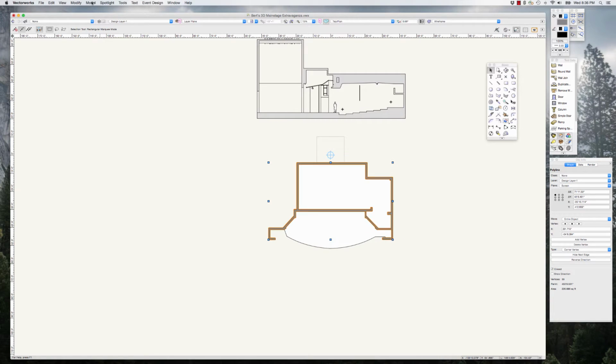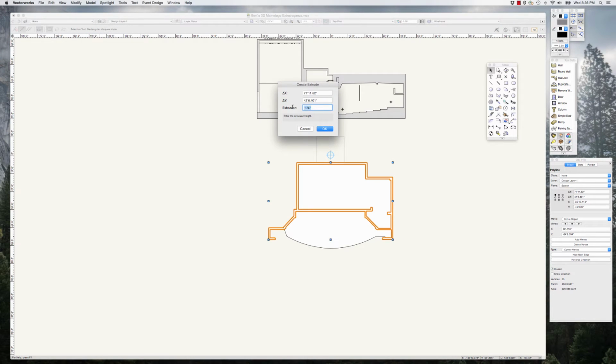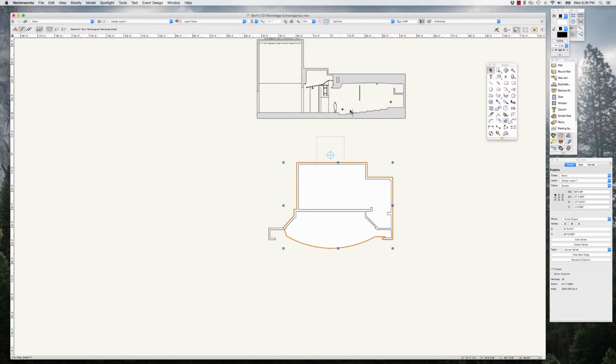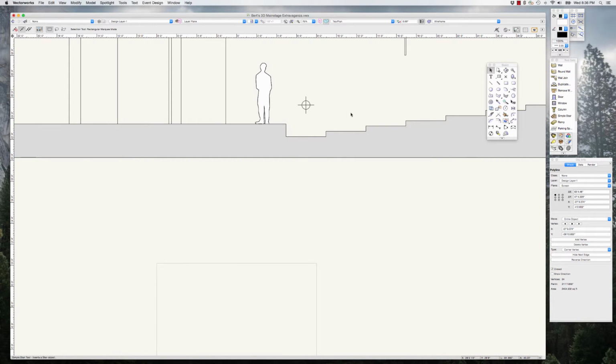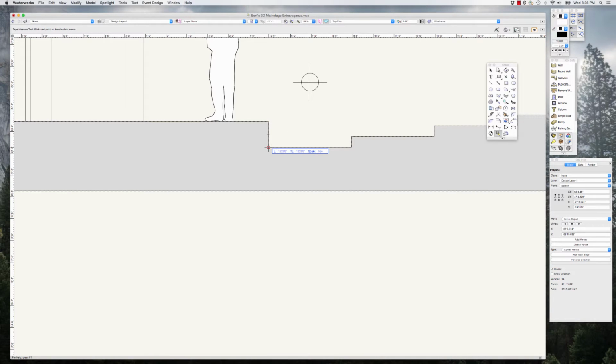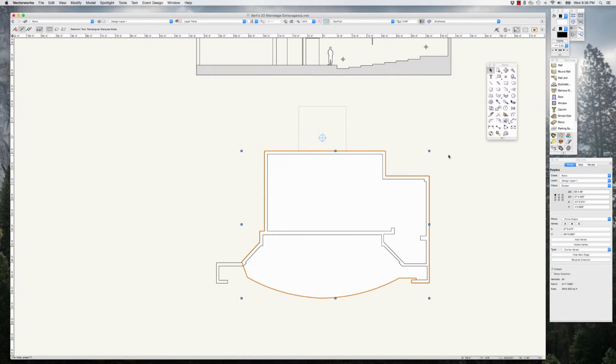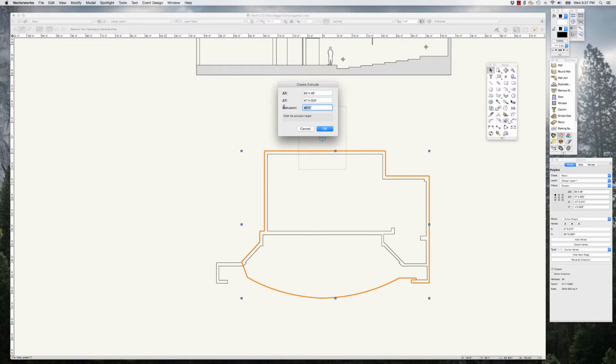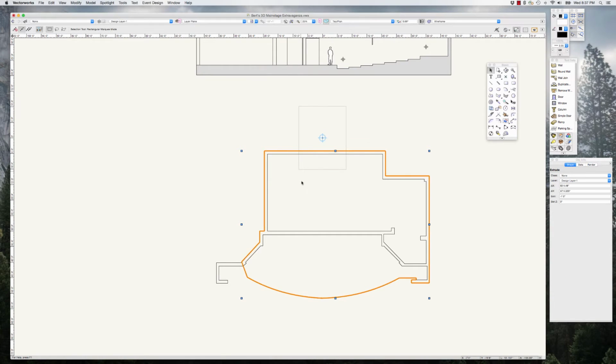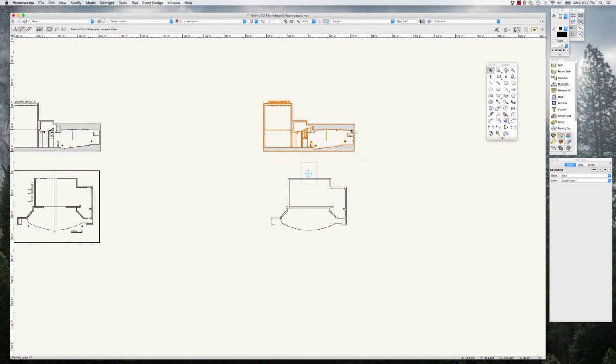So we're going to extrude this 40 feet. Model, extrude, 40 feet. Okay. And then we're going to extrude the floor down, and we're going to go down this distance, which I think is 18 inches, but I wouldn't bet my life on it. So, 1 foot 2, close. So 14 inches, not 18 inches. So we're going to extrude this. Model, extrude, minus 14 inches. Minus 14. Okay. Just going to move this out of the way a little bit.